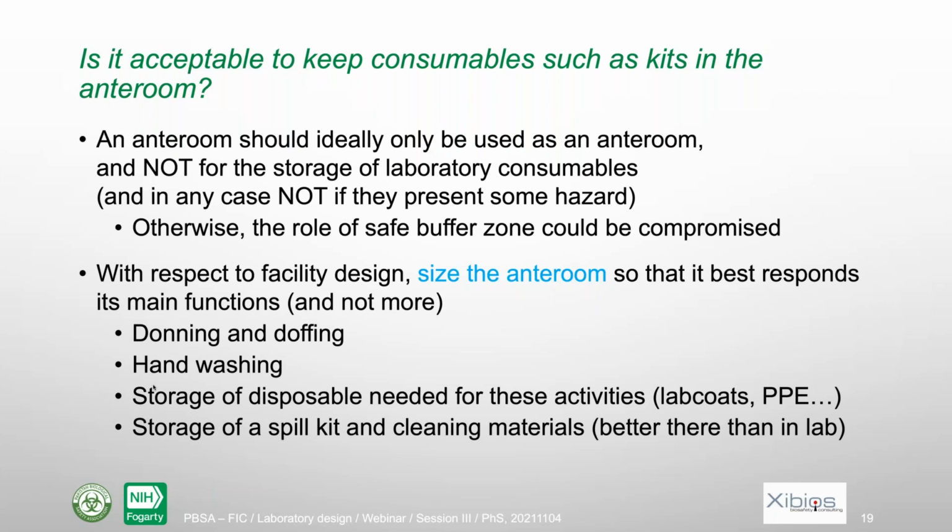So when you design a facility, you really need to define the size of the entry room so that it best corresponds to its main functions, like donning and doffing and hand washing, and also the storage of everything that goes together with this, like the disposal that is needed for that, lab coats, PPE, but also soap, for instance, for hand washing. And you could also store a spill kit and the cleaning materials, because it's better there than in a lab. But you should not make it so large that people are tempted to leave other things there.